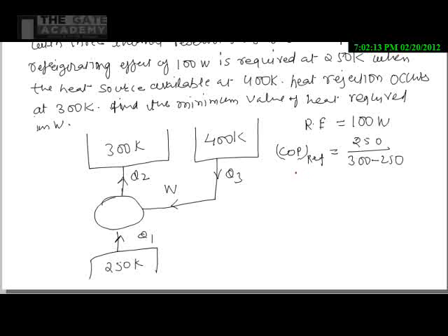COP I can also write as refrigerating effect divided by W, that is work. So it will be equal to 250 divided by 300 minus 250.